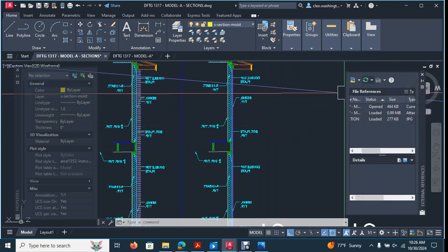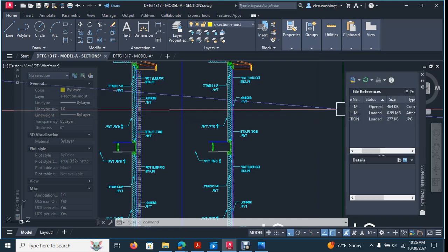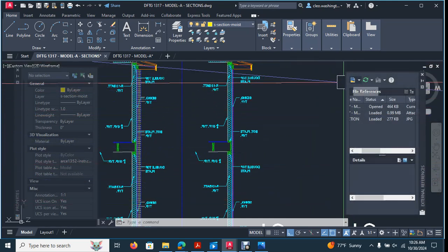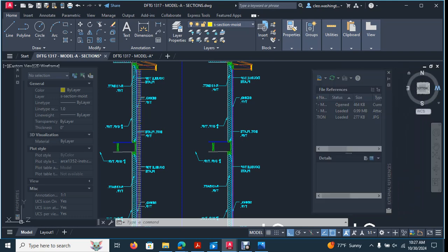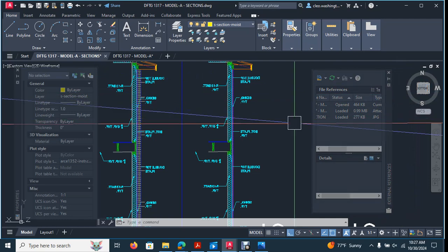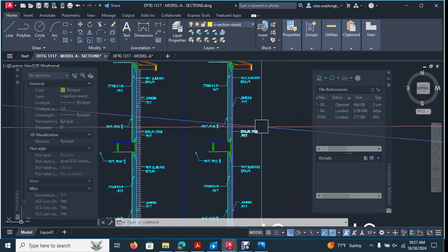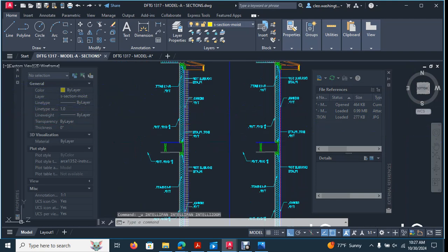That's because sometimes if you hold down shift and you drag, you will actually manipulate the 3-dimensional function. So let's go right over here to the external reference palette and move it over. You see this guy right here? Well, what happened was when I held down shift and dragged the cursor, it actually moved this. So 2 ways. You can just undo until your drawings go back right.